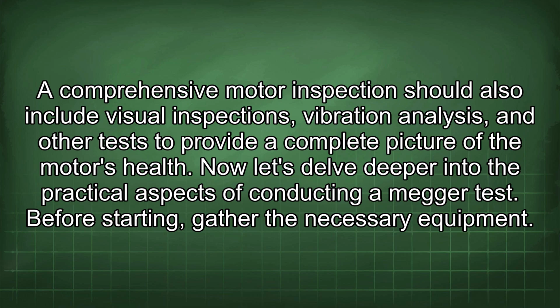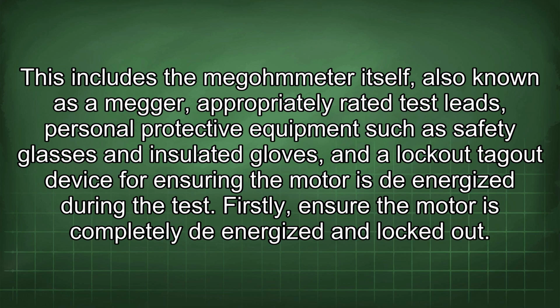Now let's delve deeper into the practical aspects of conducting a Megger test. Before starting, gather the necessary equipment. This includes the Meggometer itself, also known as a Megger, appropriately rated test leads, personal protective equipment such as safety glasses and insulated gloves, and a lockout-tagout device for ensuring the motor is de-energized during the test.